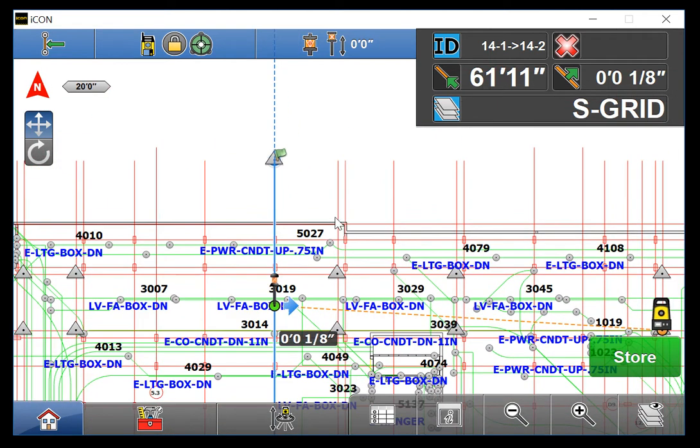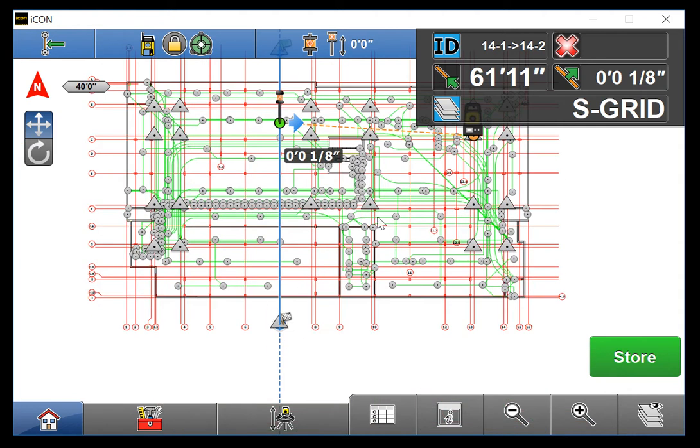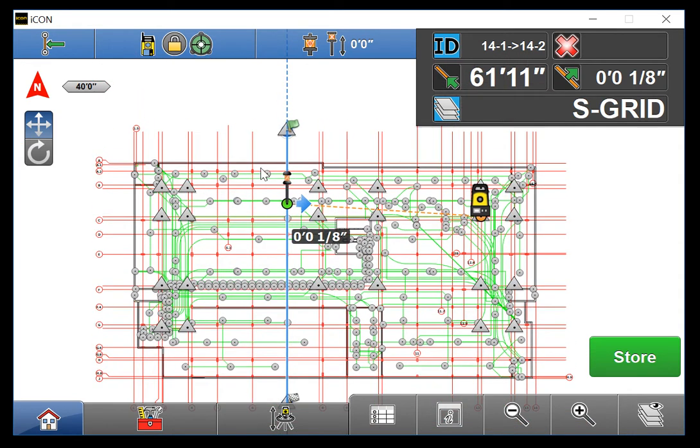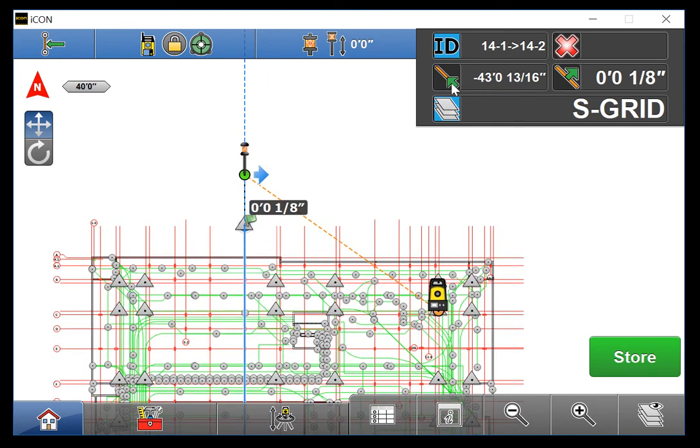Now here's the example of the stations and offsets I was describing earlier. This number is the distance in station from the green flag in the direction of the checkered flag. Right now it's positive because I'm on this side of the green flag. Notice that if I move to the other side of the flag, away from the checkered flag, it became negative. But I'm still 1/8 from the center of the line. You can tell station because of an arrow pointing down the line, and offset for the arrow pointing away from the line.